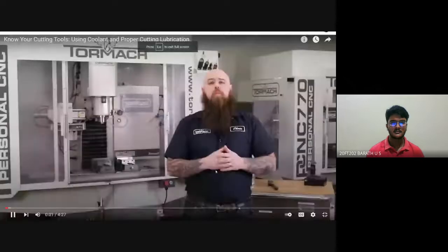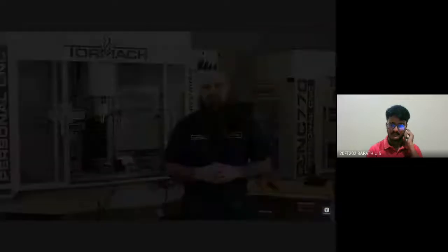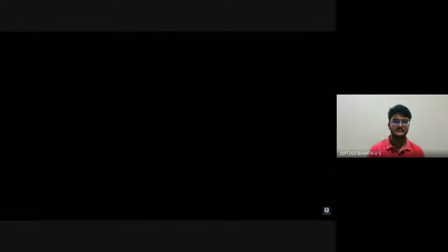Cooling and proper lubrication while machining is vital to being a successful machinist, but it can get tricky. Dealing with coolants can be a challenge, and that's not just because you're dealing with giant vats of liquid. Like everything else in the world of machining, there are a million different methods and scenarios to consider when choosing your cutting lubrication. First, you'll notice that I'm lumping lubrication and coolant together. Coolant is the term most often used, but the use of this substance is threefold: cooling your tools, lubricating the cutting process, and clearing chips.